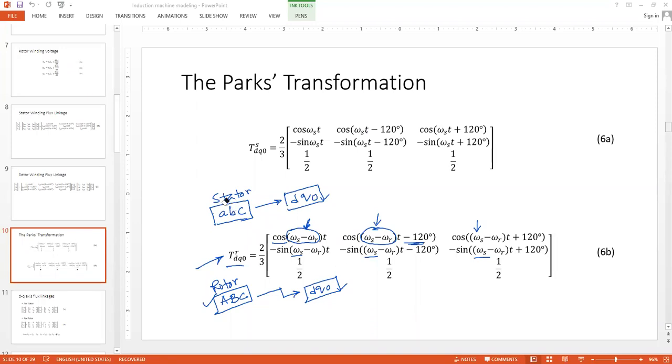So we start from some stator frame or the stationary frame. Remember the ABC coils, these are stationary, stationary in space. So if you want to represent them in terms of speed, their speed should be 0. Now, what was the speed of the dq0 frame? Can anyone recall correctly and quickly? What was the speed of the dq0 frame for the induction machine?